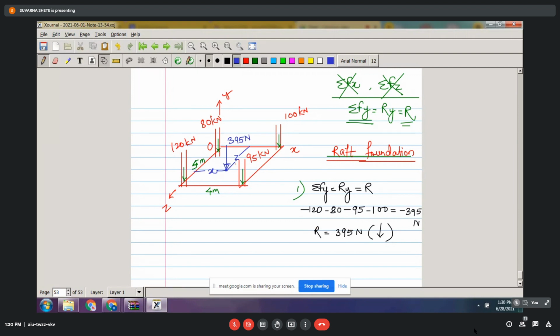Now here in this case, instead of one single point, we are going to take moments about an axis. Suppose I write the equation for Varignon as the algebraic sum of moments of all the forces about the z axis, I will call it either zz, or oz, from the origin to z.